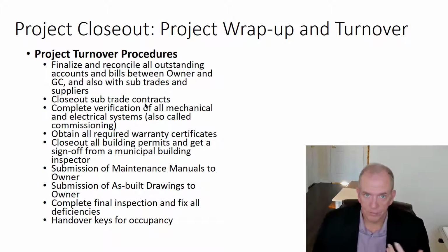that way you get the release of all the holdback monies, complete verification of all mechanical and electrical systems, obtain the warranty certificates, again that would be all in the closeout documentation, building permits signed off, submission of maintenance manuals, as I mentioned, as-built drawings.